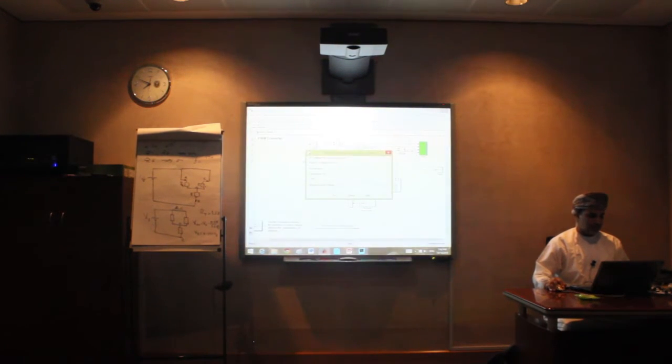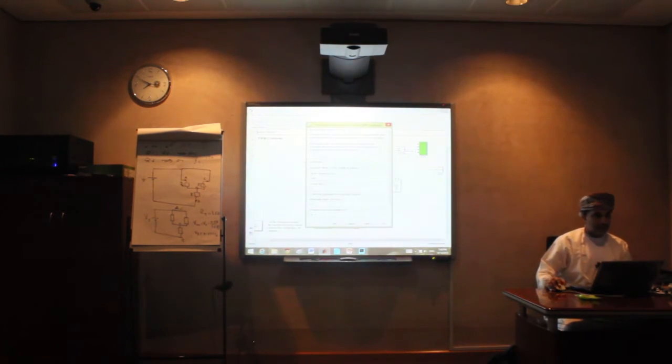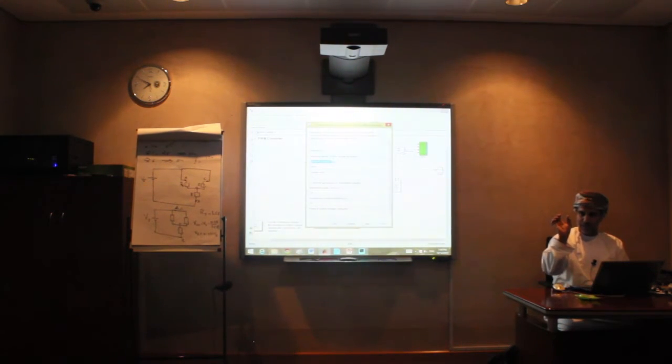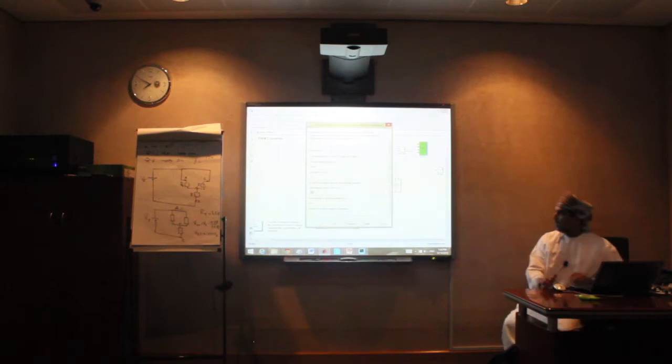This is my input. If you look at this one, it's 780 volts, right? Now, if I look at this, the modulation index here is 0.6. Okay, and the frequency of the reference is 50 hertz. And the frequency of the carrier, see this is the carrier, right? Now it's made in a block, right? The carrier is 22 kilohertz, the reference frequency is 50 hertz, and the modulation index is 0.6. Means that like this.